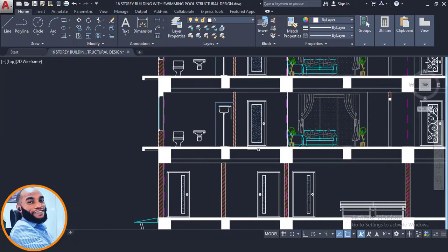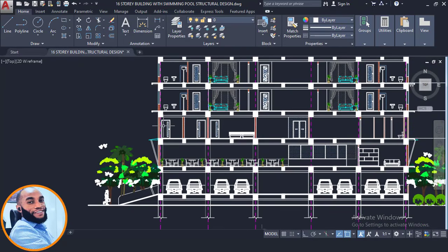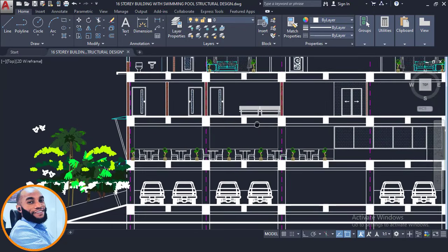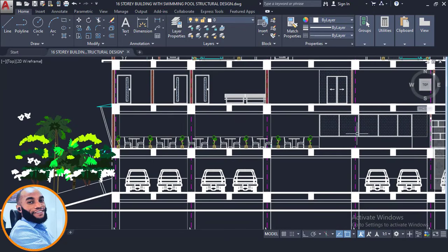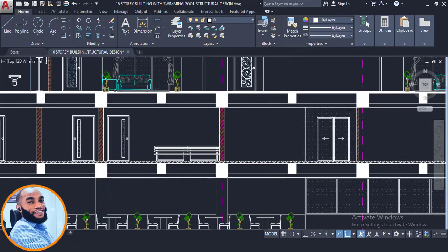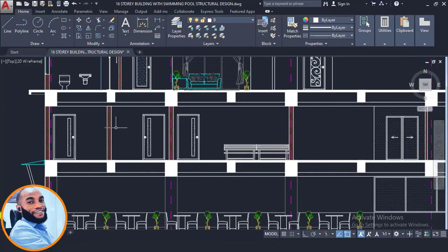That's fine, although there are some other loads. Let me see. On the second story right now we have loads. You can see that wall load is on this other side, but on story 1 there is no wall load on this internal place here. But on story 2 we have a wall load on this side. This hash here means wall load, and this side, and on this beam.